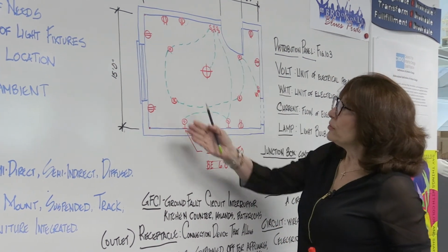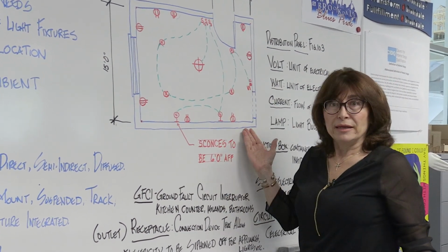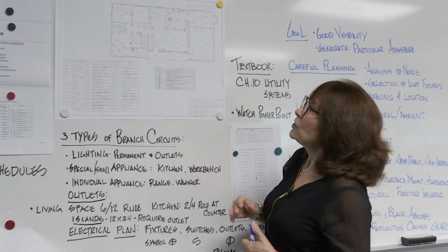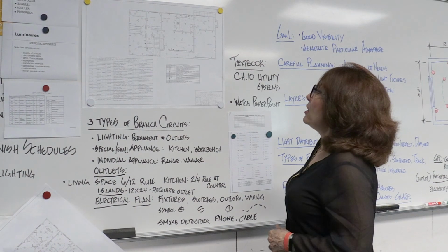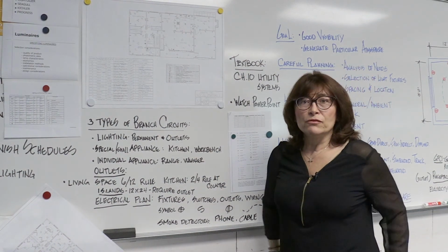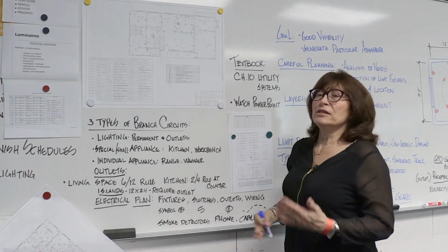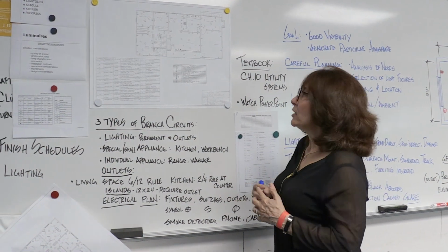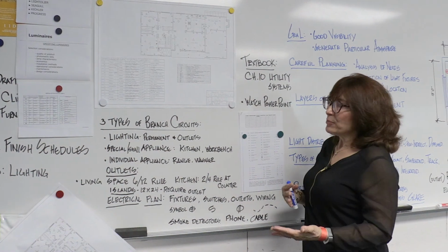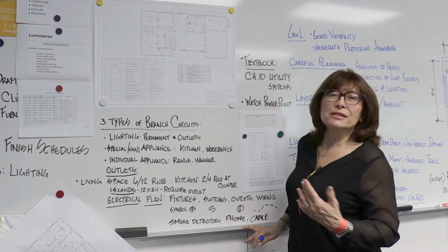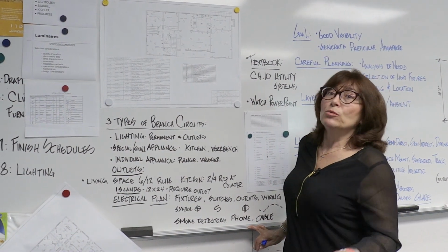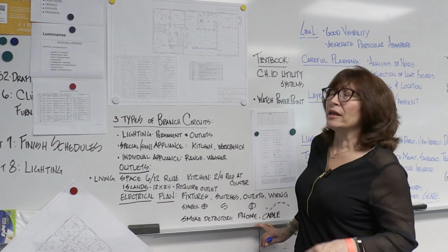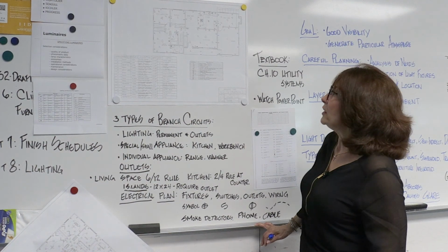And this is an example of a lighting plan. In specifying your luminaires, you want to think about the quality of the product. There's different data that the company will give you in terms of spacing criteria, lamp characteristics, meaning whether it's an incandescent or an LED. When you're looking at a light fixture, you want to make sure you know what you're looking at. So you're looking at the details of it.